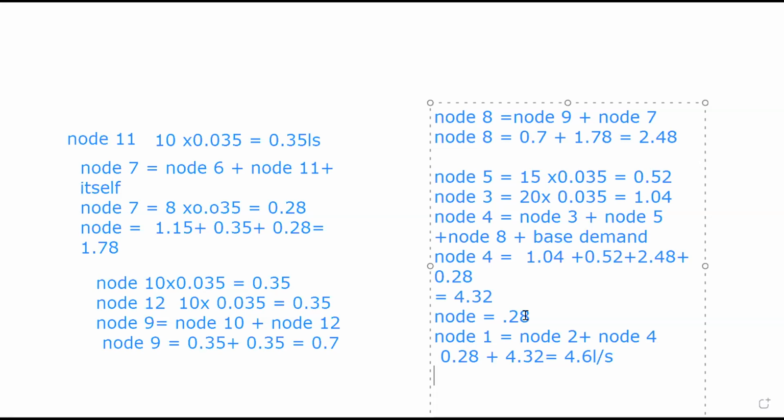So we have discretized it. What we've done, many people don't do it. What they do is they just calculate the number of houses and they get you 4.6, which is good. It depends on the scale of your design. This thing we're doing now is for the purpose of learning. I don't need to do it. What I need to do is to measure the entire area and multiply by the expected land use of the plot. I will get 2,000 or 1,000 people, and I'll multiply by the population equivalent. Remember we did it this morning for 2,000 houses or so thereabout, and we got 2.3 at a go. We didn't break down all these things, but breaking them down is just for you to understand how it is done.